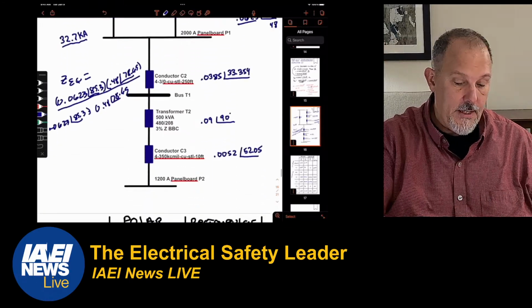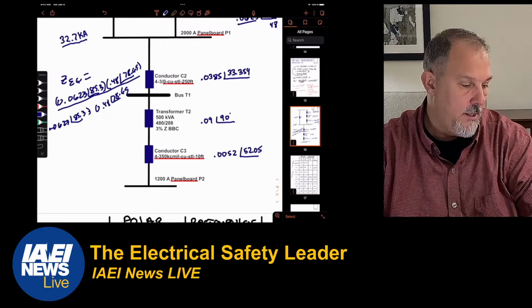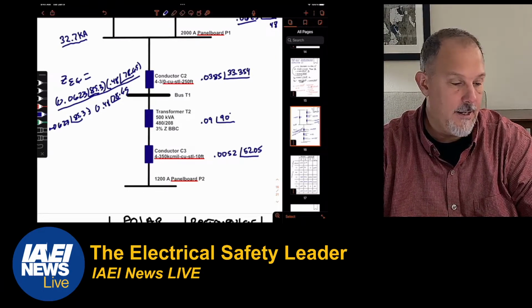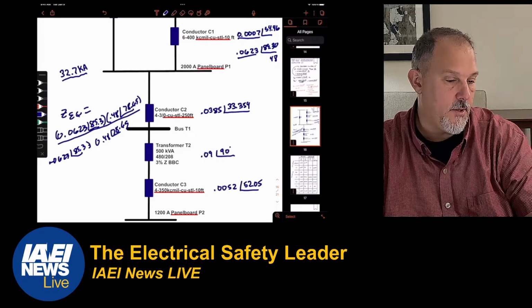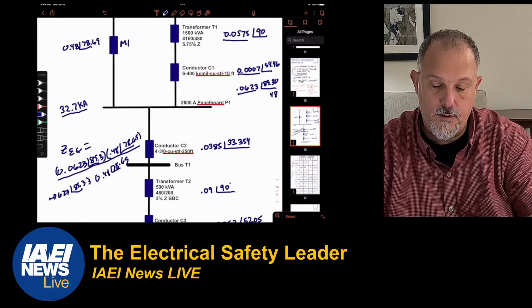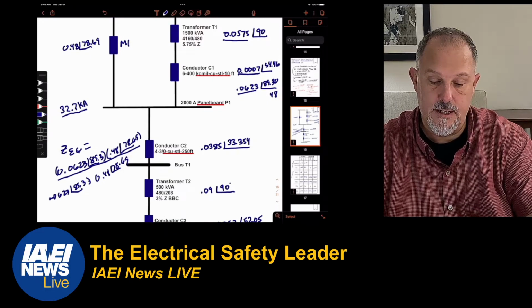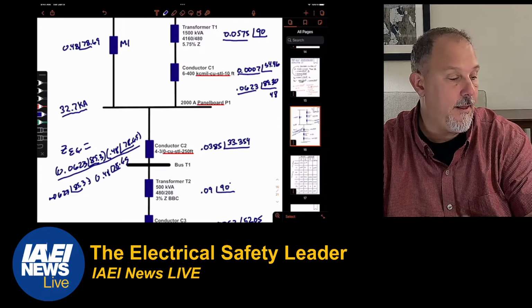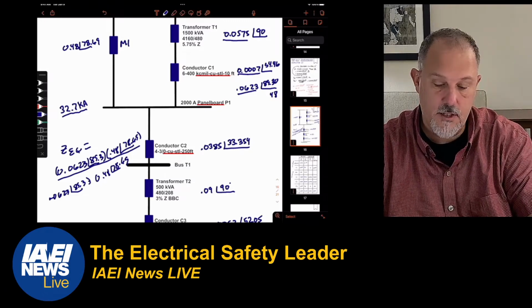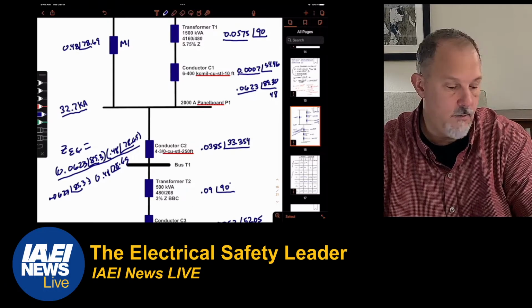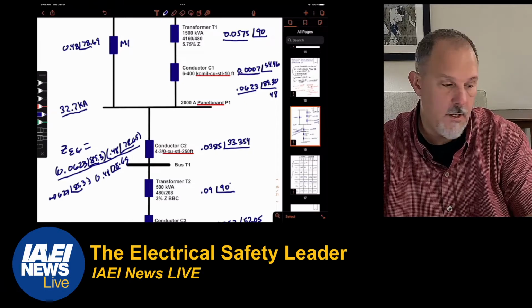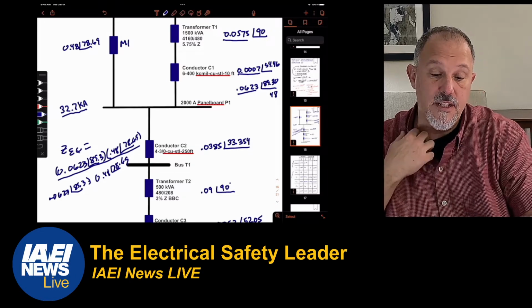And that is my equivalent impedance. So I'm going to do that with my calculator. 0.0623 at an angle of 89.3048, multiply that by 0.48 at an angle of 78.69, multiply, and then I divide by the sum, 0.0623 at an angle of 89.3048, and then 0.48 at an angle of 78.69. Add that, and then I divide those two. It's 0.055.